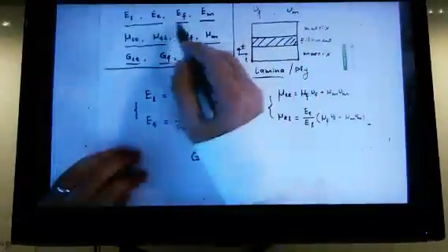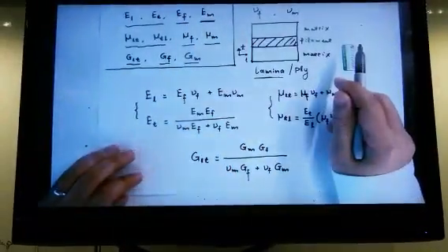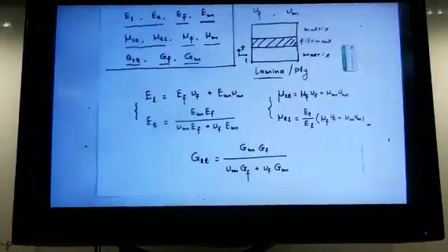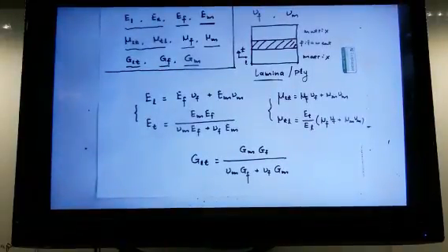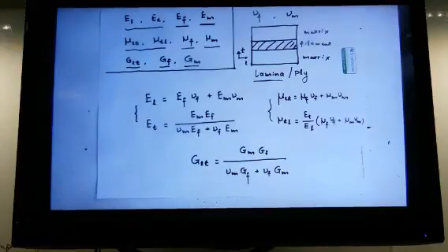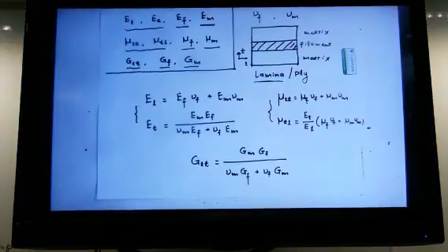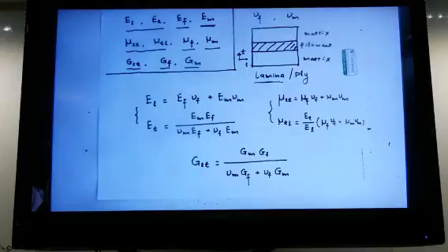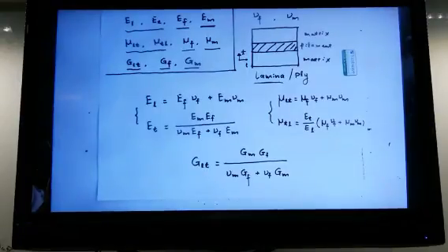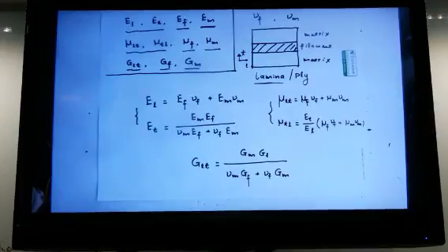And when you look at that modulus, EF, EM, why don't we have EFT, EFL? For the fiber itself, do we have longitudinal modulus and transverse modulus? We don't, because we consider that a single phase material. Fiber is fiber, matrix is matrix. Isotropic materials have the isotropic elastic modulus. Every direction, same E. So you do not have EFL, EFT, no such thing.